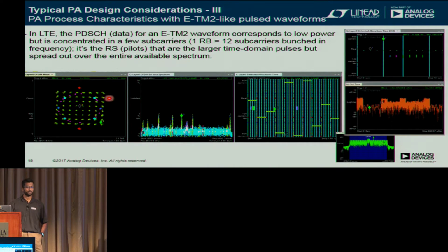And think about 256 QAM or even 4096 if you're adventurous. The 3GPP spec for data EVM at 256 QAM is like 3.5%. You won't be able to hit that. And this is an intrinsic PA behavior that your DPD solution will be expected to correct.